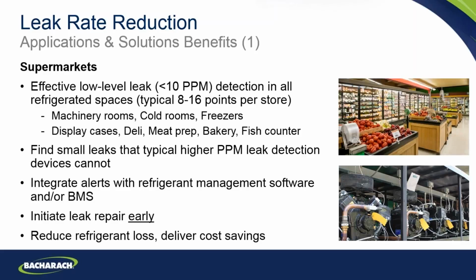It's also possible to integrate the alerts with refrigerant management software and a building management system. The key thing there is doing something with the data. Once the leak has been found, it's important that it's acted upon and there is an initiation of the leak repair to get that leak early and get it before too much gas has escaped. So this can reduce refrigerant loss, this can deliver cost savings.